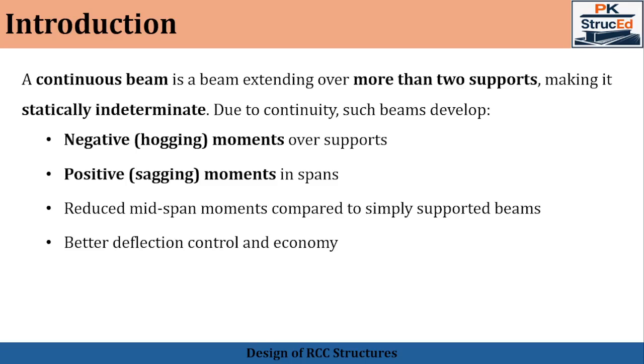And due to this continuity, negative moments, that is the hogging moments, will develop over the supports, and positive sagging moments develop in the midspan areas. So the midspan moments are reduced, deflection is better controlled, and overall designs become more economical. Here the continuity redistributes the bending moments and improves the structural performance.